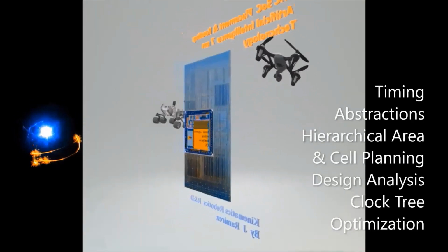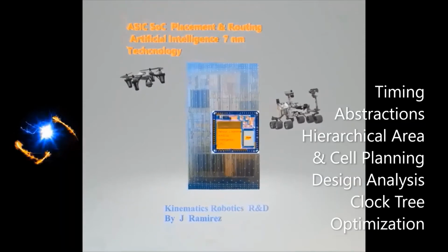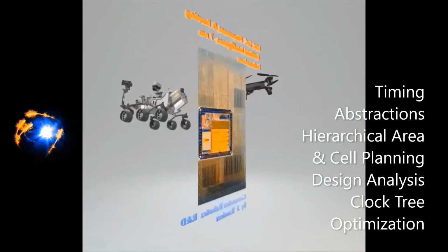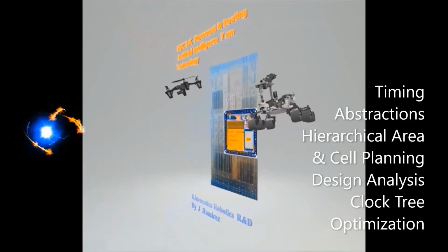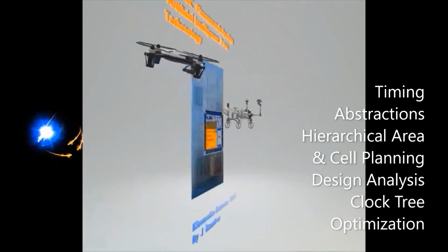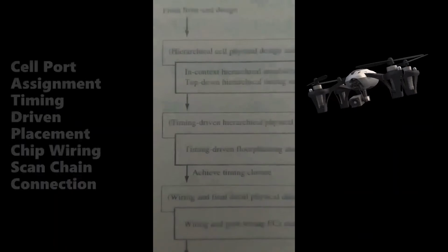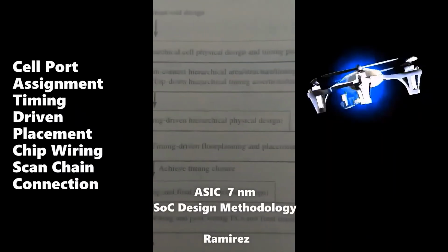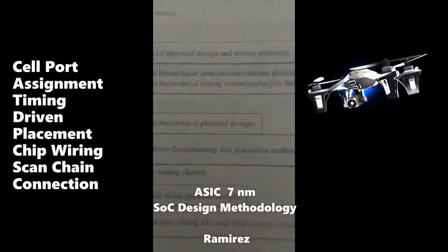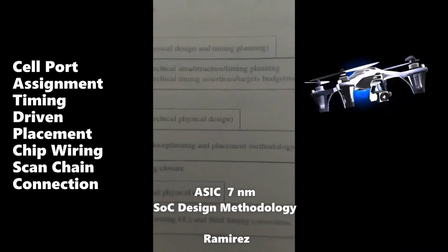Physical design methodology for the ASIC 7nm technology in the artificial intelligence system. First, identify connections to be optimized after placement so that they will not influence the placement. These include the scan and clock connection to latches.